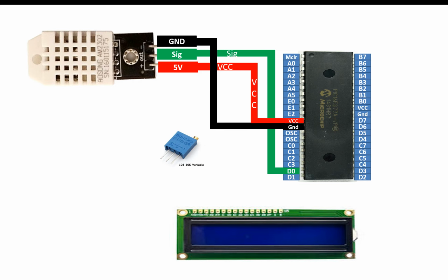As you can see, this potentiometer has 3 pins, 1, 2 and 3, mentioned on its body as well. And for the LCD, it is 1 to 16 from left to right if you hold it like this. Now guys, connect pins number 1 and 5 of the LCD to pin number 1 of the potentiometer. Then you send it to the common ground. In this way, your LCD gets a ground and your potentiometer gets a ground.